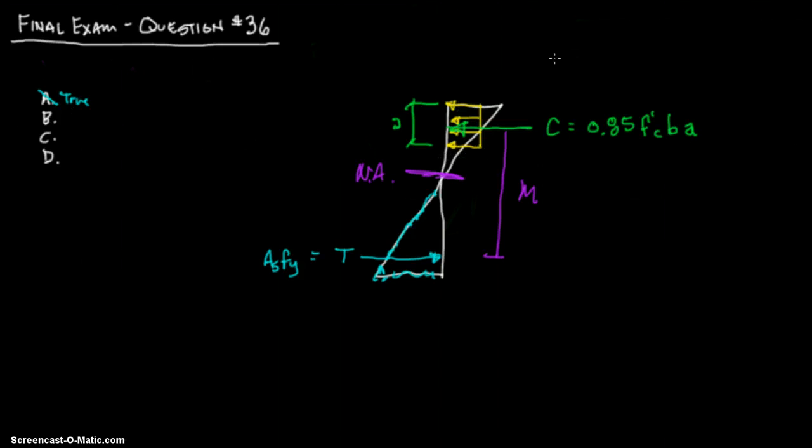You need to hold this at strain equal to 0.003 for design, and that pretty much matches up with your yield stress. You don't want to go over this. If you do, then your concrete will crush, and you will have a catastrophic failure.